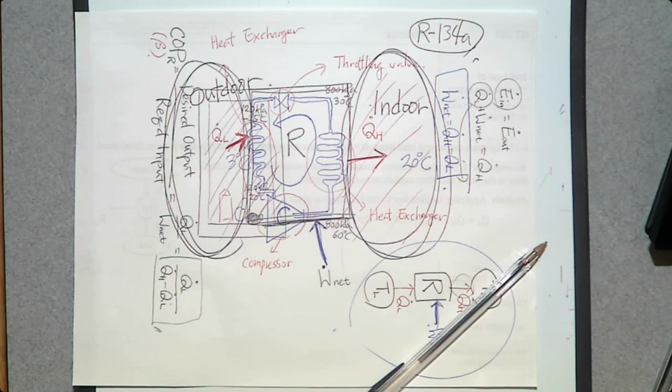You need to throw it away. To where? To inside. So you open the door and locate your refrigerator facing outside. You're cooling outside the whole way, and you're heating inside. Because when you run a refrigerator, you absorb heat from the food, and put that heat to outside, which is indoor. That is a heat pump.